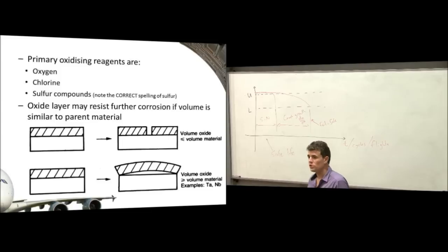So for steel, which you would be familiar with, rust tends to flake away off the surface of a rusting component. That's because iron oxide rust is bigger in volume than the steel that's underneath it. So once it starts corroding, it actually exfoliates and peels off the surface and exposes more iron to rust. So it's a repetitive process. More and more material is corroded.